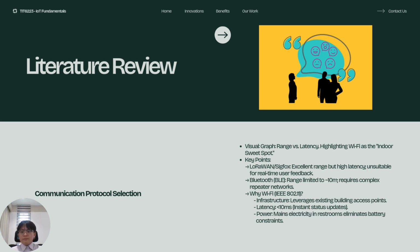So for connectivity, we perform a comparative study of wireless technologies. We analyze LPWAN protocols like LoRaWAN. While they have a great range, they suffer from high latency and low data rates, which makes them unsuitable for a system that requires instant red light or green light updates. We also reject Bluetooth due to its short range, which is not scalable for monitoring from a distant management office. We conclude that Wi-Fi is the optimal protocol for indoor environments like malls and airports.